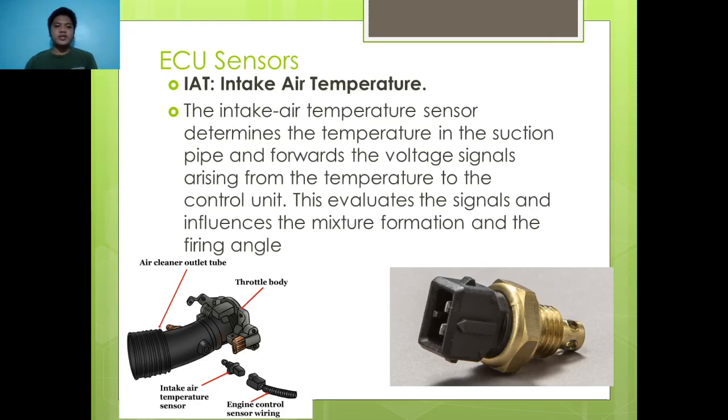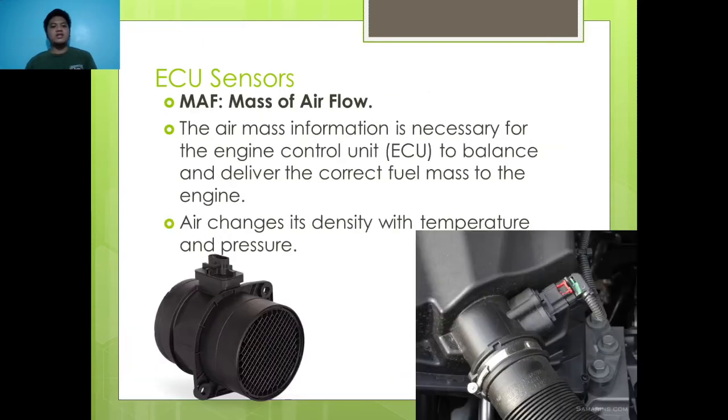Intake air temperature. The intake air temperature sensor determines the temperature in the suction pipe and forwards the voltage signals arising from the temperature to the control unit. This evaluates the signals and influences the mixture formation and the firing angle.